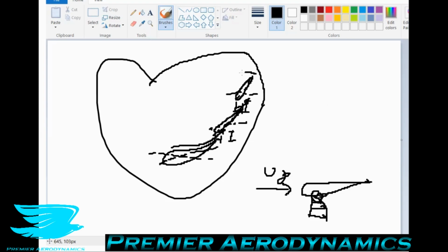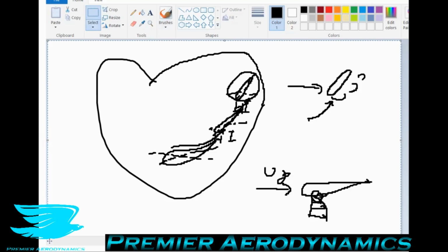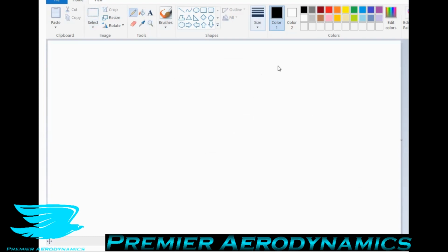So if we were to take just this third element, for example, which is at a very severe angle of attack, let's say it's at, I don't know, maybe 60 degrees, if you were to have a regular airflow hitting it straight on, that's definitely going to stall because it's just such a massive angle of attack. However, because it's behind a second airfoil, the air coming from the second airfoil is actually directed up. So now the actual angle of attack, the effective angle of attack between this third element and the flow it sees, is much less than 60 degrees. So that's why the flow can stay attached and the airfoil will still produce a lot of good lift.